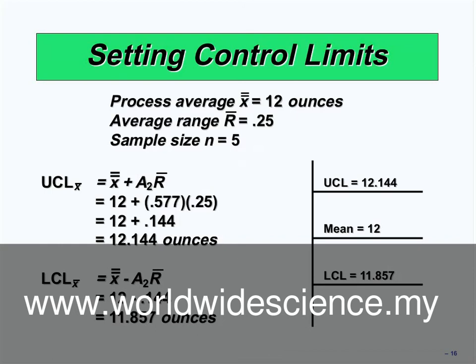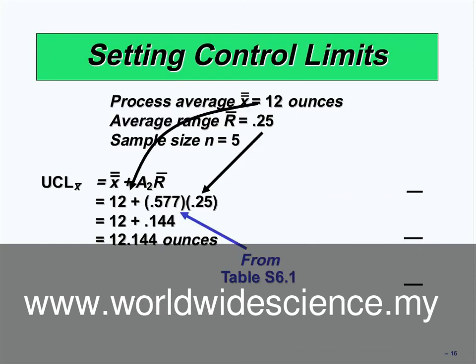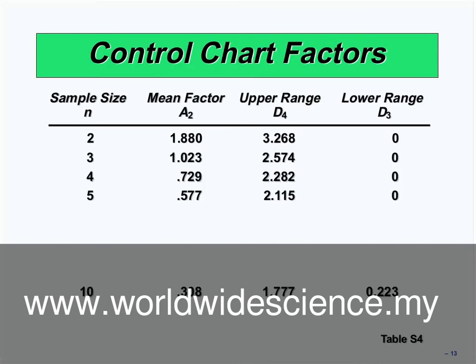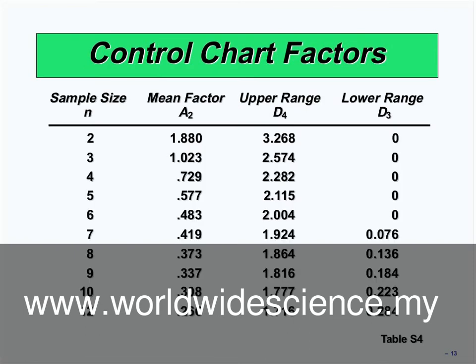As I told you, R or range should be calculated in each hour. Range is the difference between maximum and minimum in each hour. For example, in hour 1, the maximum number was 18 and the minimum number was 13. The difference between 18 and 13 is 5. If you calculate the same for all of the other hours, for example, the range was 5, in other hour 2 the range was 6, in hour 3 the range was 5.